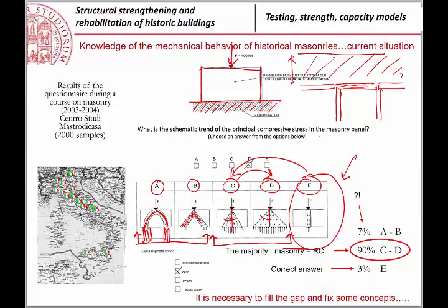Why? Because the stiffness of a wooden beam is very small with respect to the stiffness of the masonry. So, in this case, you start having a distribution which is something like an arch behavior, because the beam is weak in terms of stiffness. But the case that was subject to the engineers was the case of a rigid foundation.